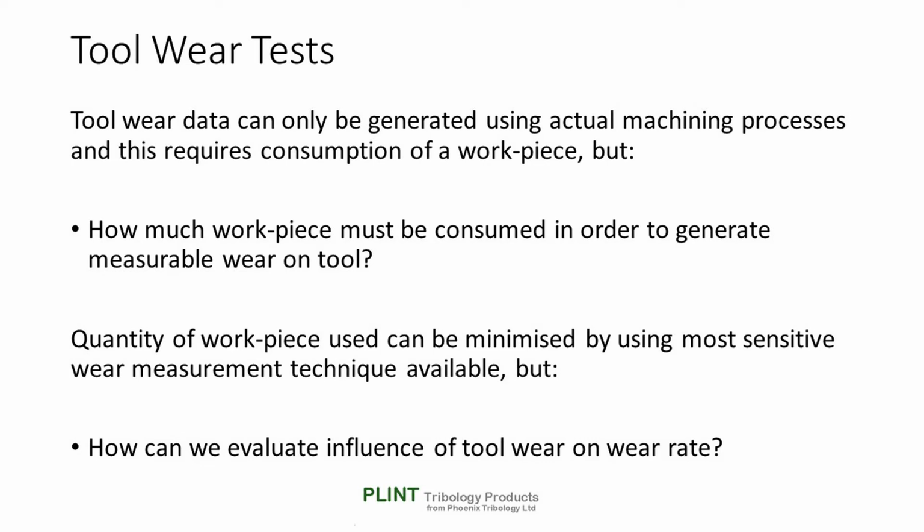The difficulty of both generating and measuring the wear, most probably using instrumented machine tools and substantial quantities of workpiece material, leads one to consider whether there may be simpler measurements that could be made that may indicate the wear behavior. There is evidence that tool wear is related to chip tool friction and also an increase in tool temperature.